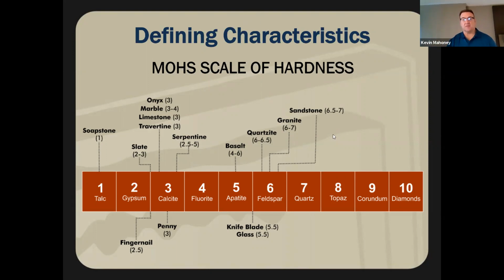Ask your folks. Granite, on the other hand, in the floor as pavers, is much more resistant to scratching, even though it's a little bit lower on the Mohs scale. So quartzite, a very, very durable product used for countertops, floors, inside, outside, pavers, is very resistant to scratching. So just because it's harder doesn't mean it's best.